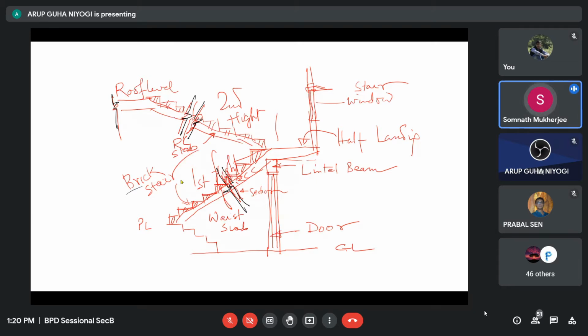I have told that in the bedroom, front room, or the bedroom and veranda, doors will be slightly more, and in the dining room you can put a double window. The single window size will be 1000, 1200 or something like that, and that can be joined together to make 2000 millimeter width, or it may be 1500. So the window will be a little larger in the dining hall portions. Or if it is a large veranda, then you have to provide a double window.